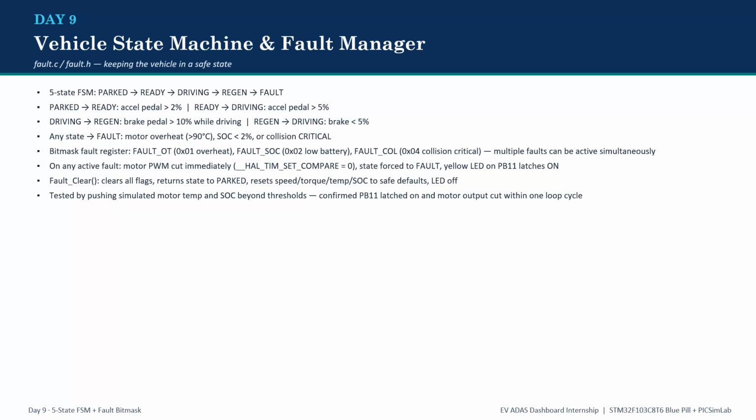Specifically, when the motor is overheated above 90 degrees Celsius, or the battery SOC is dropping below 2%, or a critical collision warning, then it triggers the fault state. I implemented this using a bit mask fault register, so multiple faults can be active at the same time. Fault OT for overheat, fault SOC for low battery, and fault collision for